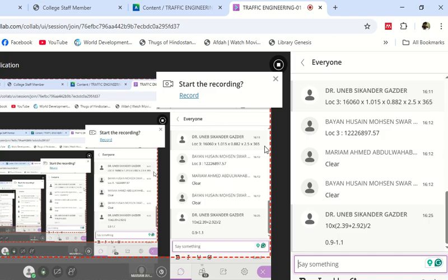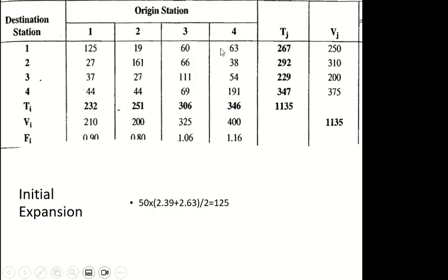If all the factors are in this range, all the factors meaning all the columns and all the rows. Sorry, it is hidden here, but all these factors, so 250 upon 267, 310 upon 222, all of these should be in this range, and all of these should also be in this range. Now this is not shown here, but you see this one is not in my range, this one is not in my range. So that means I need another trial.